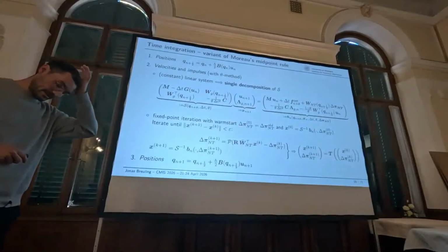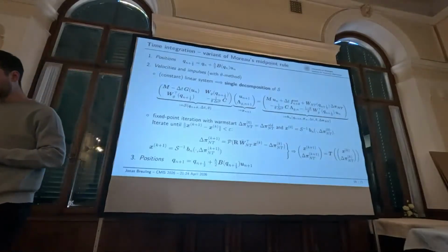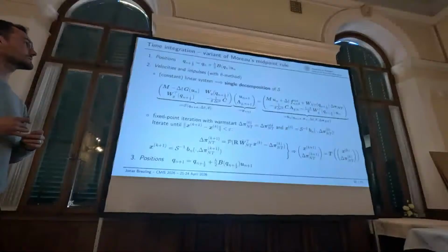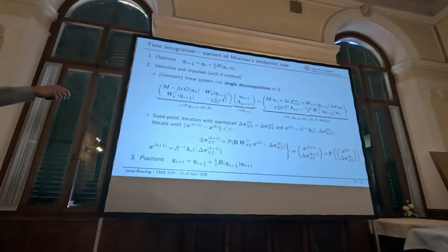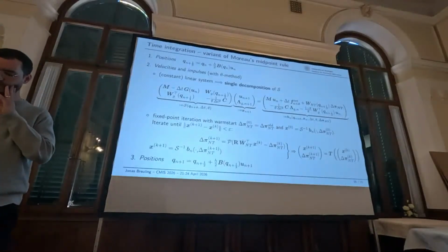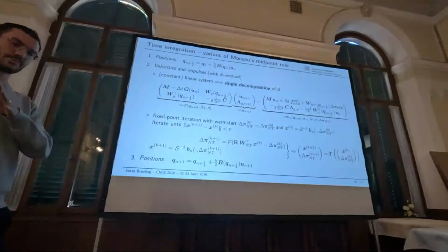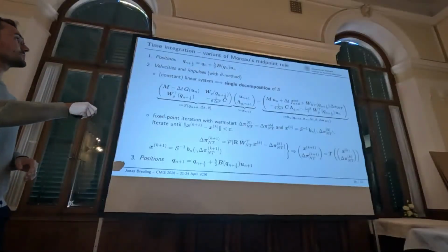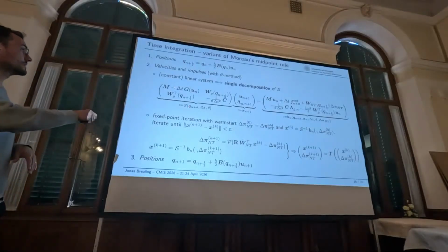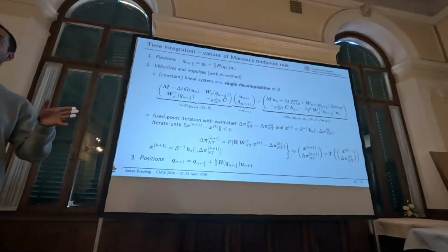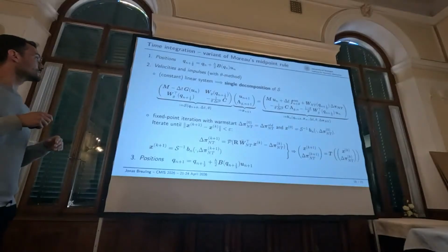And now this is a really huge slide because I do not want to go into details of the integration method here because it's quite difficult, but its basic structure, I think, is clear. So we have 2 position updates, the first one with the half step and the last one. And obviously the magic happens inside, the second point. So the idea is to separate positions and velocities. So after the first half step, we freeze all the positions, do all the collision detection, evaluate all the involved matrices here for directions of forces, of what else do we have?